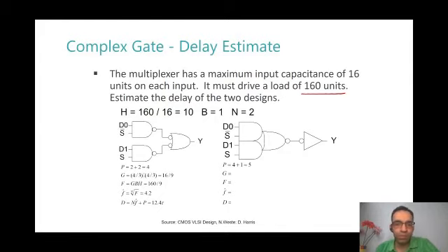You can quickly make this gate and find out its G. You will see that G is equal to 2. F is GBH, so 20, because H is 10 over here. And what about total delay now? Total delay has increased a little, 14 tau.